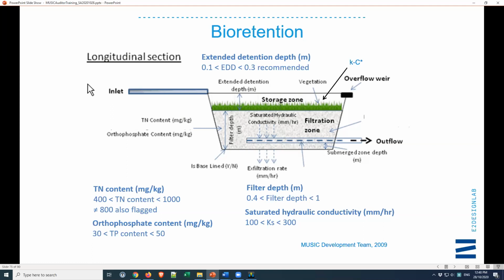The lower range of that is 100 mil, and one of the reasons for that is that with streetscape systems, what we see is people trying to get clever and they say, well, we can only do 50 mil or 20 mil of extended detention. So they model that in good faith. In practice, the contractors come out and they build it. That level looks much like the next one. They fill the gravel up to the surface, and before you know it, there's no extended detention in your system at all. In fact, it's not uncommon to see them overfilled. So we've set 100 as a minimum because that's enough to be obvious to the contractors that it's not meant to be at the same surface level as everything else around it, and you're more likely to get a successful system.